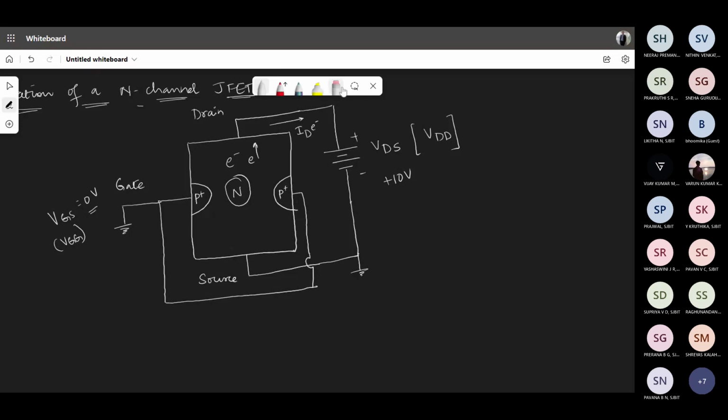But normally when you write the current direction in a semiconductor device, we always write the conventional current direction, so it should be like this, getting in, but otherwise the electron current is coming out. So the supply will take out all the electrons in the channel, and that forms the electron current, which is ID. But the conventional current direction is into the channel, which is the hole current. So the current will come out like this as again ID. The same ID is flowing everywhere, and this ID indicated here is because of the hole.